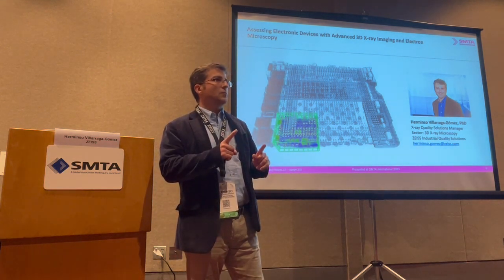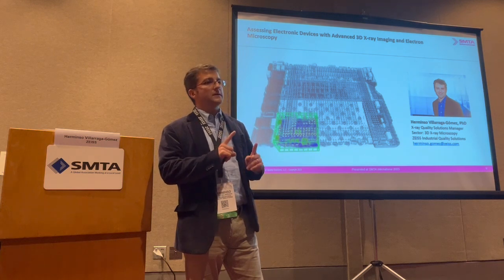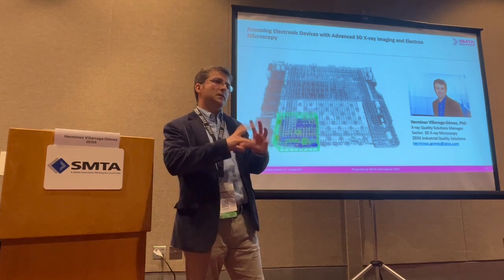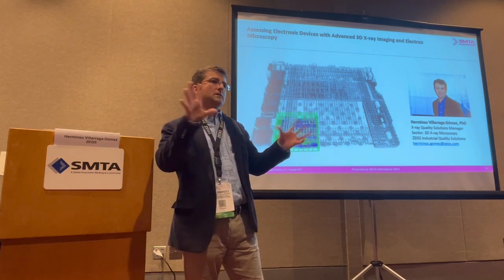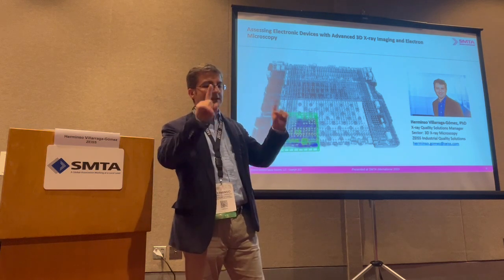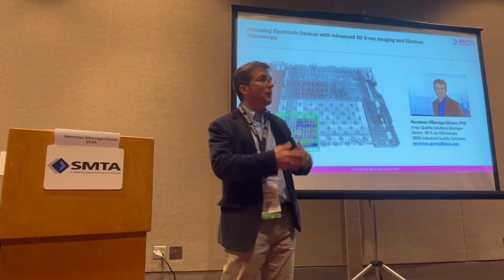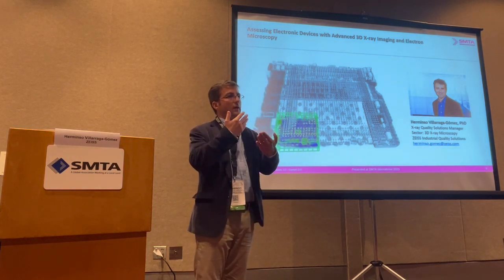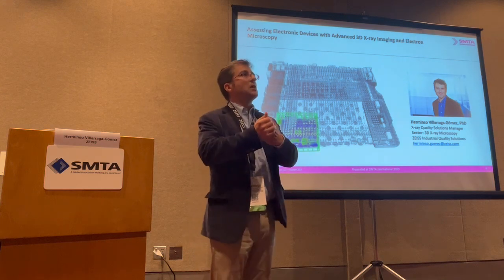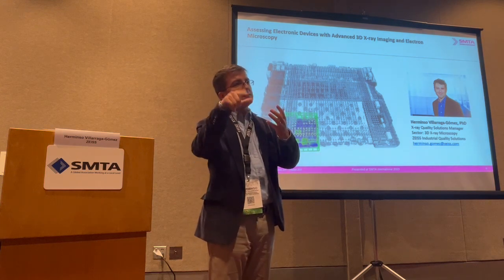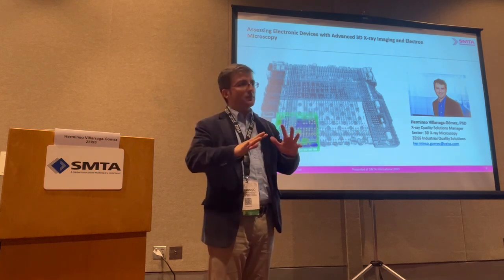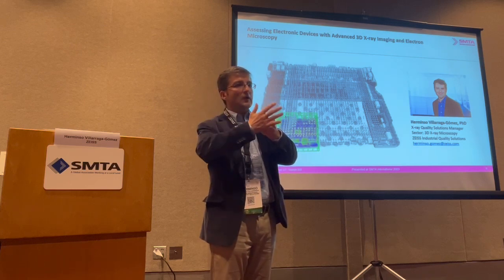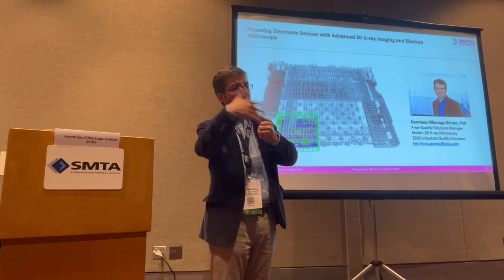Yes, you have to be careful with that, but more than looking for the voiding, I will look for the type of features. So let's say you're looking for BGAs, not looking too much for the vias, then you will try to do the training in a section that has that. Those might have voiding, and that will be ideal. X-rays basically work in terms of contrast, so what you tell is a void is because you don't see material there. So that will be great, but it's not necessary because you still will have other regions of the scan that have no material that can tell what will be noise.